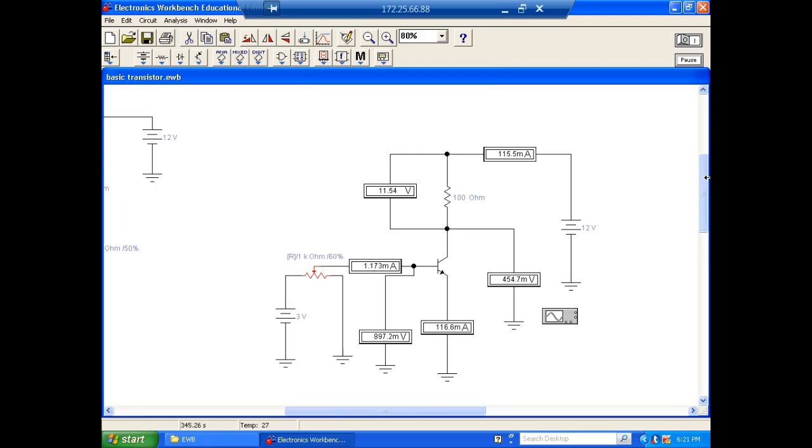1.5. This voltage is going down, this voltage is going up. But we're pretty close to saturation right here. So the top resistor is dropping 11.83 now, 11.84. So we're saturated right now. Okay, we're saturated now.